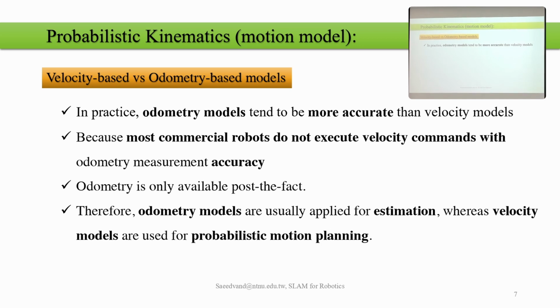You say, okay, if my speed is this, the robot's angle is this, and it is moving in this direction. We will see how to calculate it if it's rotating also. But here you can read it. I can read my wheels. If it's a humanoid robot walking, you can read the step sizes, accumulate them, and finally get the rotation and where I ended. Because of that, this is more accurate, but in most applications we don't have access to this, and we have to use the velocity model.